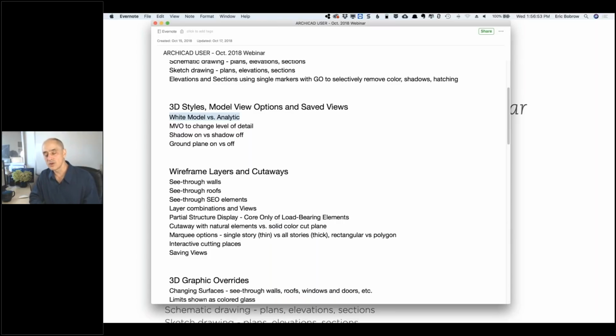Well, the first thing you can do is to just work on a copy of the file. So if you take a copy of the sample project or duplicate it, you can do anything you like because you can always open up the original one and look at that. In general, what makes a template functional are the layers and layer combinations, the fills, all of the attributes, the fills, building materials, composites, etc. I would never delete a layer or a layer combination until you're really experienced.